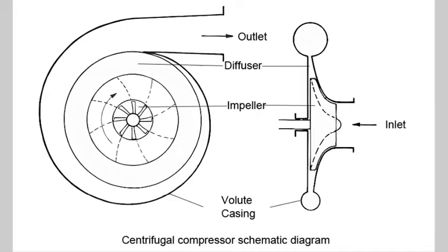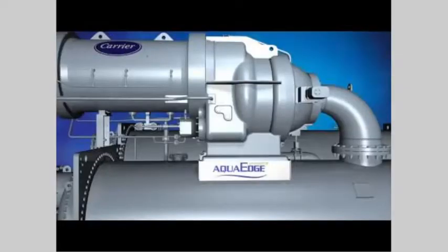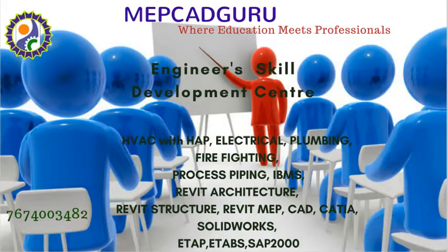The main advantage of the centrifugal compressor is that there are no valves, pistons or cylinders. The wearing parts that need attention are the main bearings. The centrifugal chillers are manufactured in capacities from 90 to 2000 tons. Selection criteria. Energy consumption per ton of refrigeration is highest with reciprocating machines, followed by screw compressors. Centrifugal compressors consume the least power at full load operation.